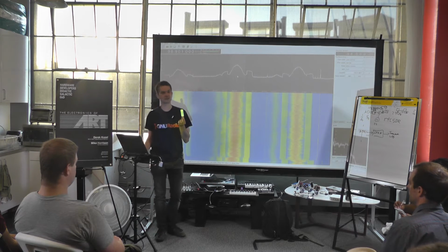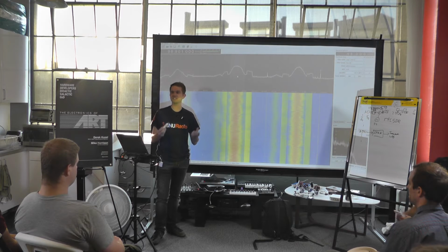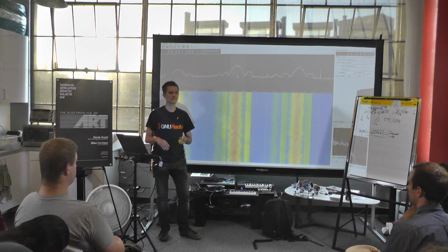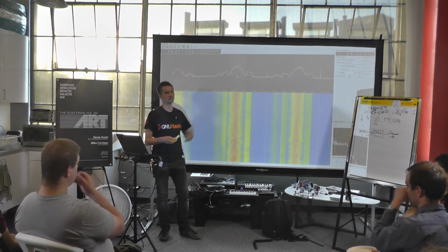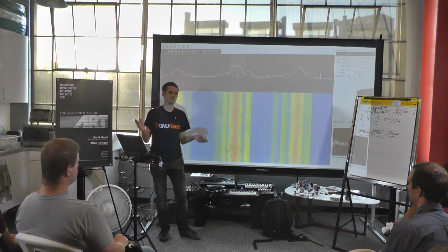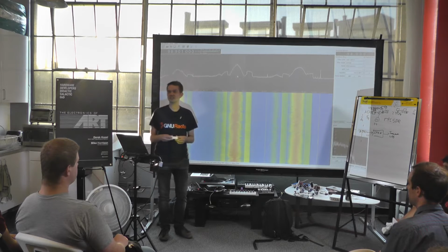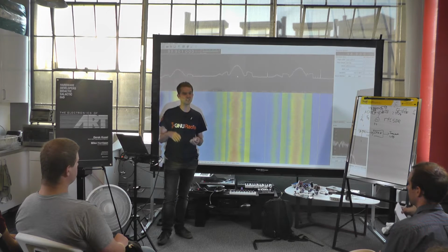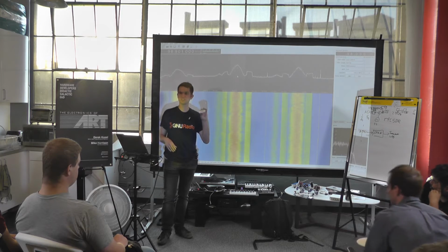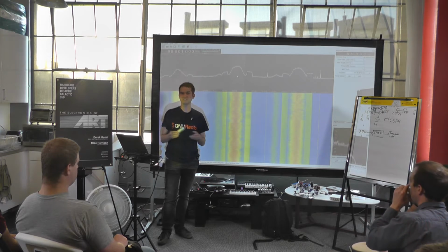The chips inside this were originally developed to be a digital TV tuner. So you're supposed to be able to plug this into your computer, hook it up to a little antenna, and watch TV. Somebody figured out that it was actually just spitting out raw samples of the radio receiver. And so you can write a little bit of extra software and demodulate FM. Or you can demodulate AM. Or you can demodulate a cellular base station, a satellite image. So if you were at Maker Faire and came by our booth, we actually had an antenna running, downloading satellite imagery using one of these. You can track planes, a whole bunch of different things.